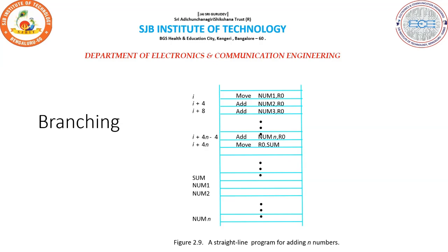Then within the body of the loop, the instruction Decrement R1 reduces the content of R1 by 1 each time through the loop. The execution of the loop is repeated as long as the result of the decrement operation is greater than 0. The branch instruction loads a new value into the program counter. As a result, the processor fetches and executes the instruction at this new address, called the branch target, instead of the instruction at the location that follows the branch instruction in sequential address order.